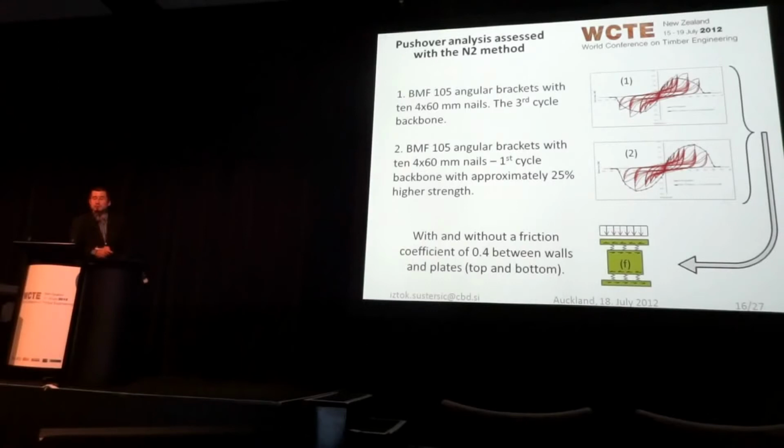Just a short comparison: if we weren't using friction, the average displacement after all the 7 accelerograms was 44 millimeters. If we compare that to the results from the displacement-based design, we are quite close. However, if we use friction, we shoot off by almost 50%. But still, SAP is not the best tool for nonlinear dynamic analysis, especially if you're using very specific hysteresis behavior.